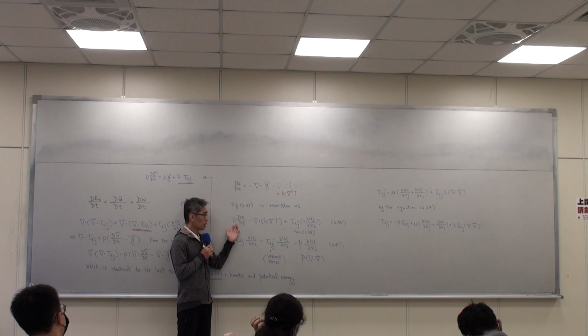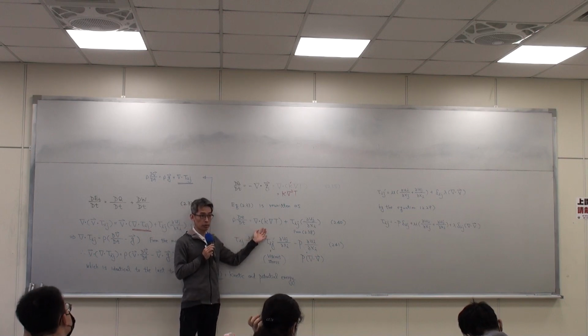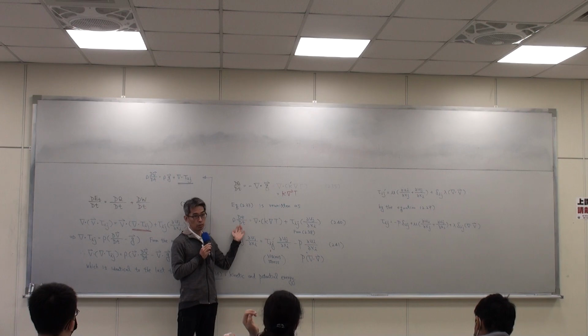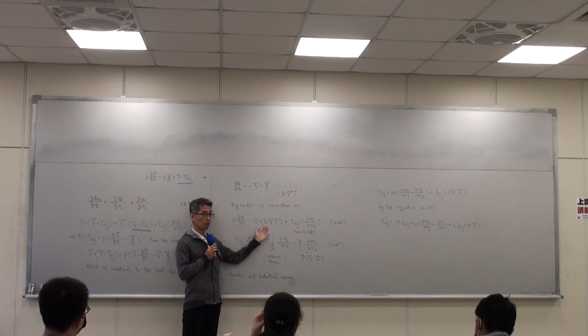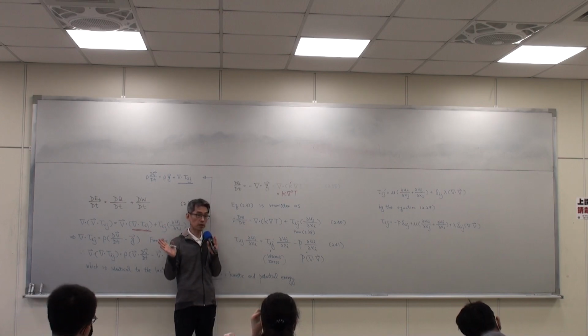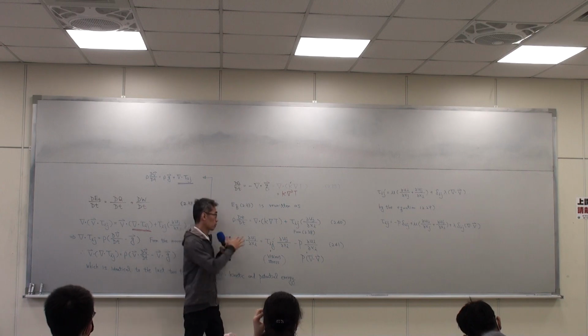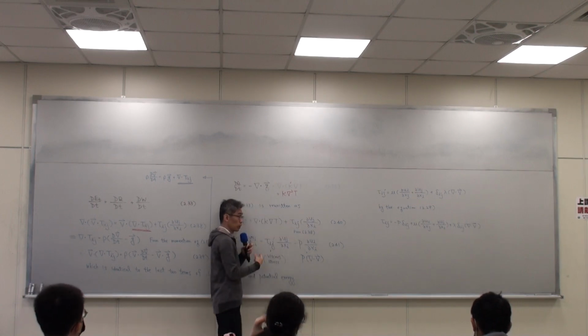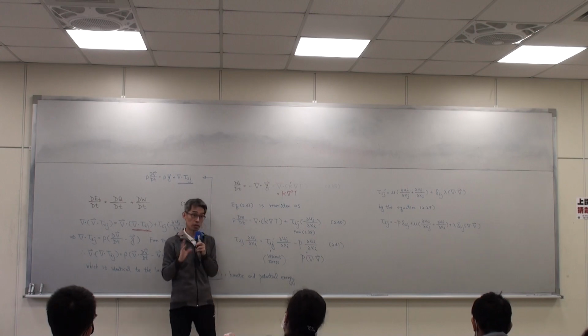In a very special case, if there is no temperature difference, should the internal energy change or not? If you don't have a flow field, and don't have a temperature difference, that means there is no heat flow. So this term should become 0. And as long as this term becomes 0, that means your internal energy doesn't change.